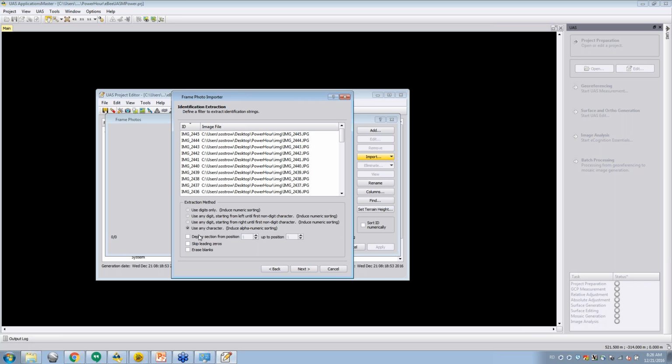So if I have a varying height, like it's a mountainous area or anything like that, is there a recommended way I should come up with that terrain height? That's where you want to consider which part of the project you want to process to. So if you want to calculate the bottom of a pit, you should use that. If you only have ground control points at the top of that pit and you really want to process for the bottom of it, you should actually use the bottom of the pit elevation. Okay.